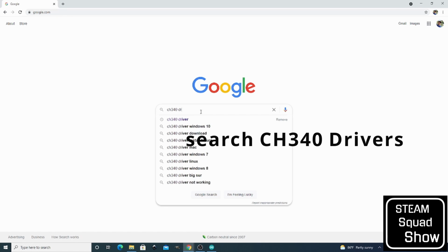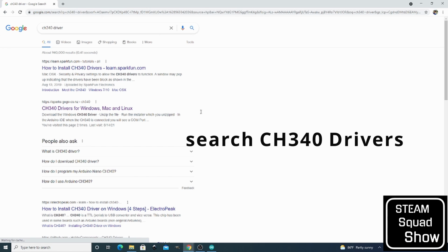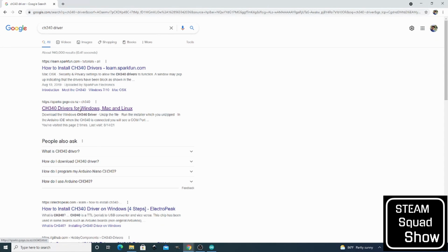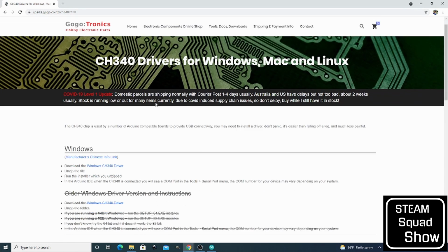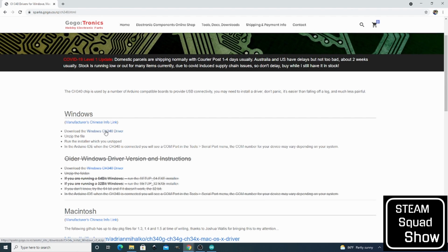What you're going to need to do is go and search for CH340 driver. All right, and I go to Google and I type that in, and I look for this link right here. Now I'll put the link in the description of this video, but you will click here. This will take you to this web page where they have the drivers for your Arduino. So what you're going to do is you're going to download the driver here. Once you do that, you're going to find it and install it on your computer.